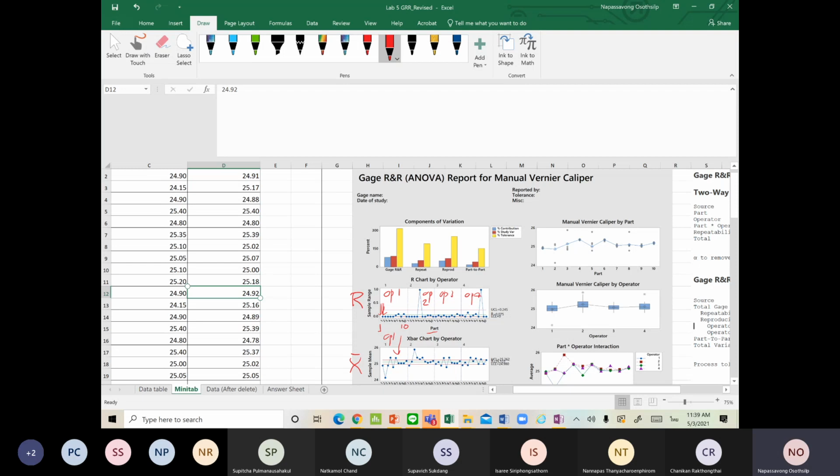The first thing that you need to know is that each R number represents sigma in terms of repeatability, because it's the difference between the 2 measurements. And X bar shows you the dimension, how large or small the dimension is that you measure.